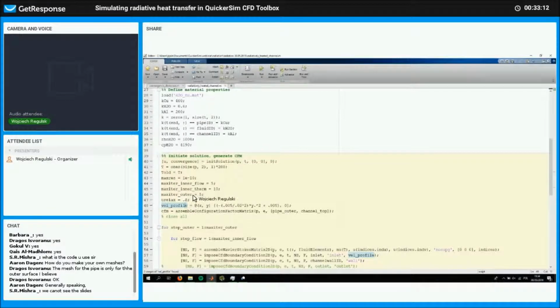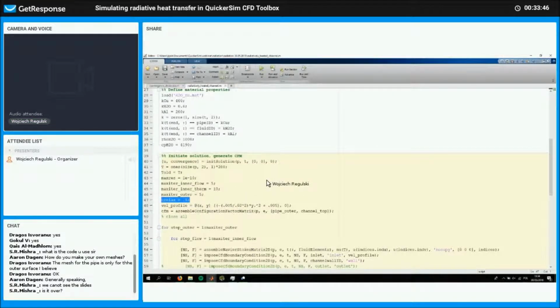Okay, the U relax is the under relaxation factor for radiation. I'm going to be talking about this in a little bit when I get to how to converge our solution, because radiation has a bad habit of oscillating back and forth, or actually blowing up very easily. So you almost always need to under relax your thermal or heat transfer when you're using a radiative boundary condition.